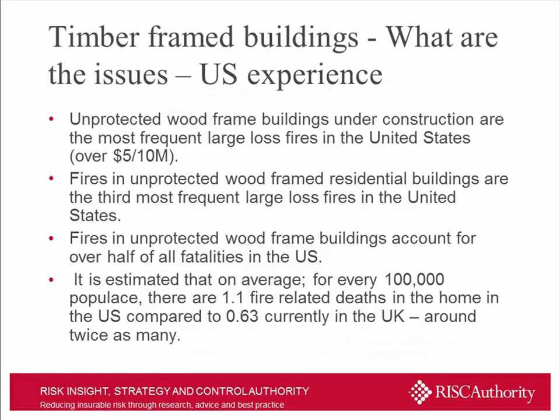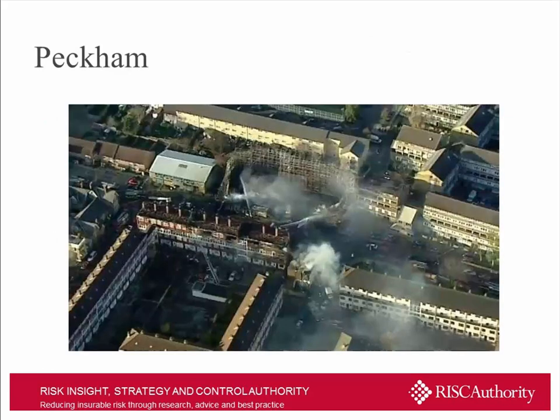Timber frame buildings, we're seeing and continue to see increased use of timber frame as a construction method in the UK. You very often hear that we're told that, well, they do this all the time in the US, don't they, and they don't have problems. Well, there are just a few statistics there which tend to debunk that. Unprotected wood frame buildings under construction are the most frequent large loss fires in the United States. Probably don't need to go into any more detail than that, but the slide goes on to describe various other statistics that are related to the completed buildings and the problems that continue to exist in that respect.